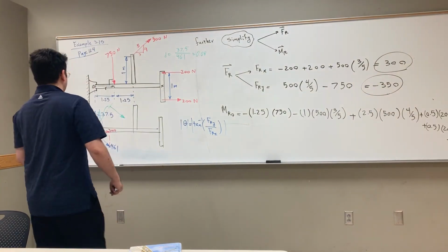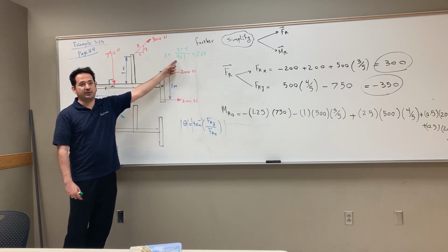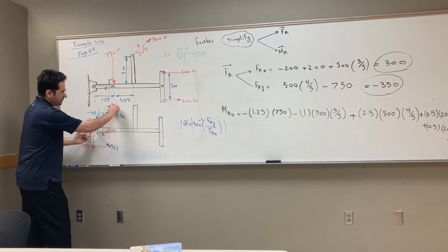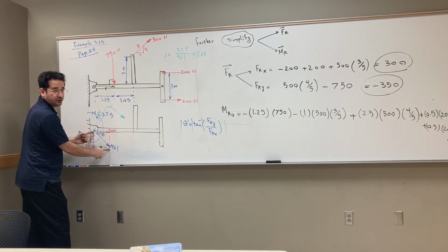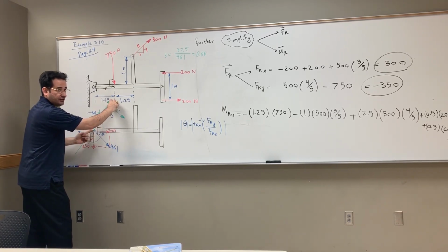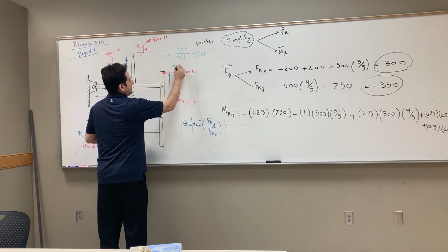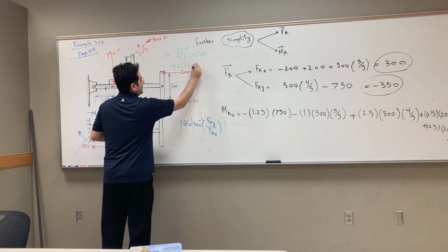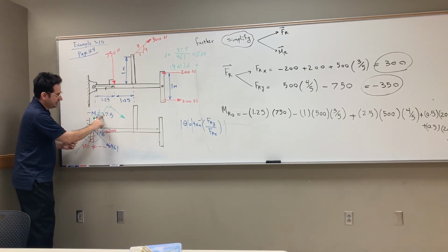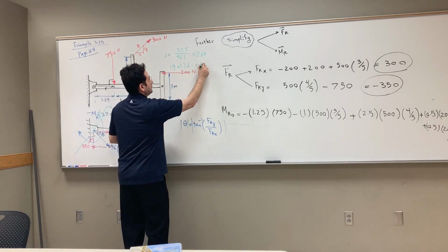All right, so what he wrote here is another expression for moment. So D times 461 is the moment generated by the force. Why? Because the value of force is 461 times this distance that we shift this force, right? So 461 times D, this moment should be equal to what? The moment that you already have here. What's that? 37.5.